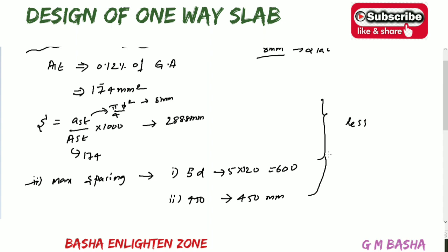If you observe the distribution reinforcement, the spacing will be 288 mm. How much reinforcement are we providing? The minimum reinforcement which is required in the distribution reinforcement. So that will be 174. Based on that the spacing will be 288 mm. And here maximum spacing allowed will be up to 600 mm and 450. So we are providing whichever is the lesser value according to our Indian standards.